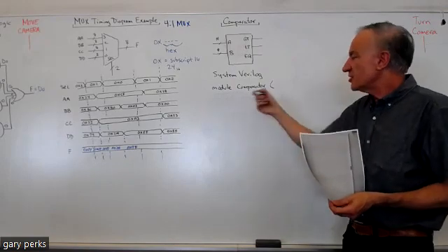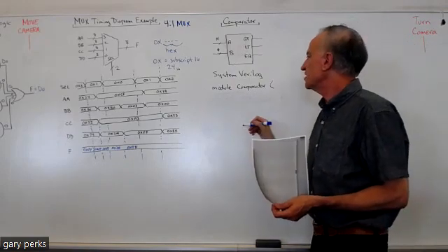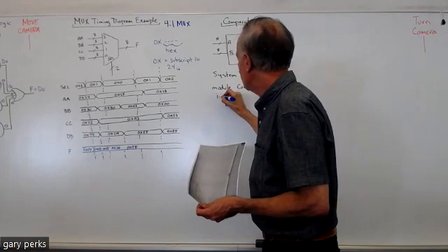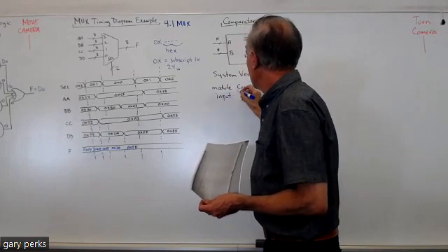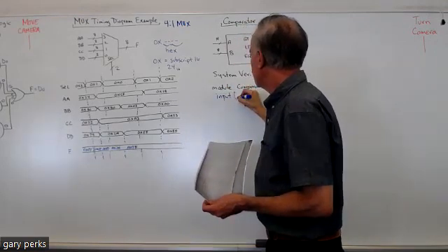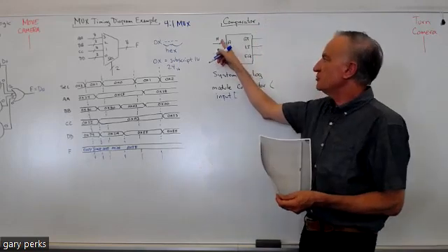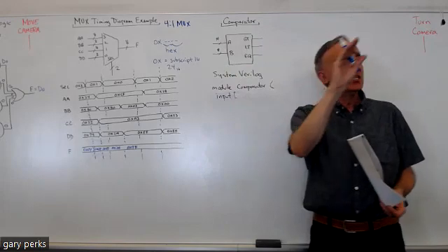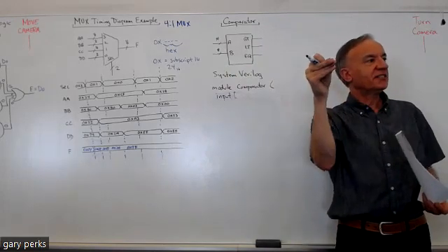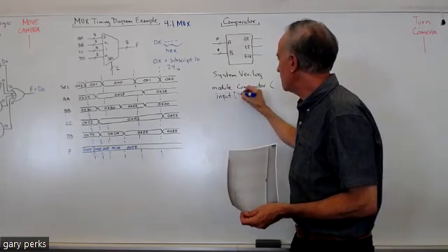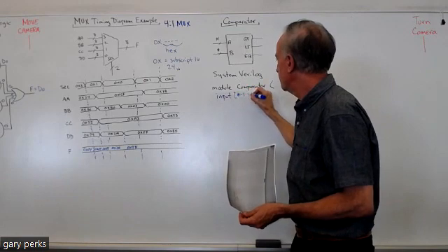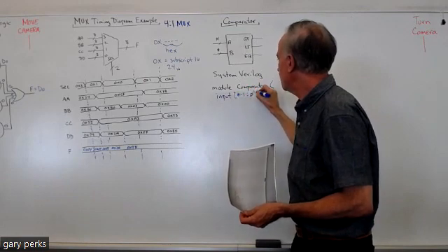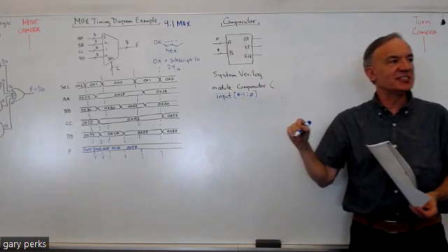You're going to have to declare your inputs just like you've been doing. For example, input: since it's multiple bits, you'll need the square brackets. Again, I'm doing this in a general sense. So whatever this number is, you would put that number minus 1 for your high number, and then you put 0, because we always call the least significant bit 0.